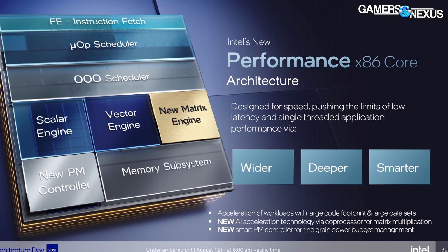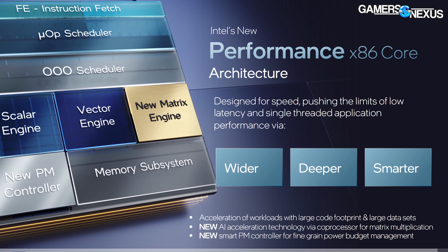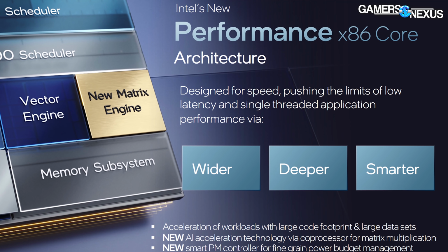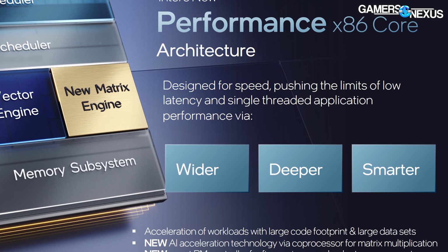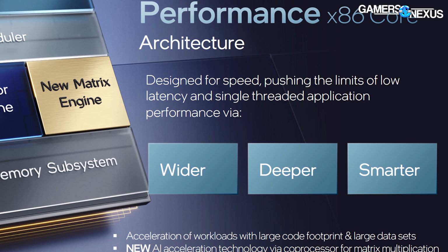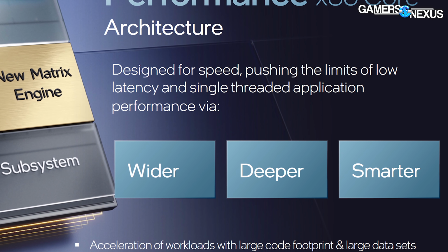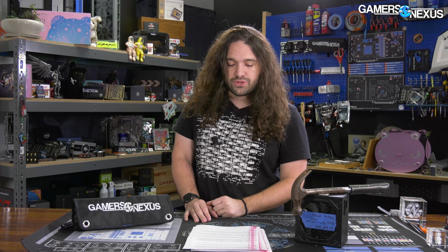The performance cores use x86 architecture. They were designed to expose more parallelism and to reduce latency and support large code and data footprint applications. Intel's tagline for how they reportedly accomplished this was to make the cores wider, deeper, and smarter. For clarity, everything for the next couple minutes or so will be about the P cores specifically, and then we'll draw a hard line so you know when we switch over to the efficient cores, because again, they're different. That's the whole point of them.